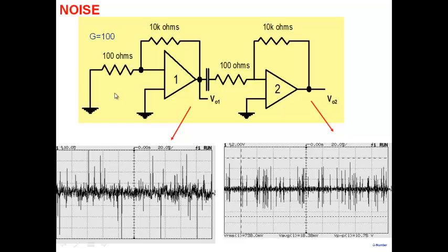It is coming from the fact that every resistor that you see here is a source of noise. This resistor is generating noise. This is generating noise. All of them are generating noise. By the way, the capacitor also has noise, because it has a resistance in parallel and other things. But more than that, if you go inside the op-amp, you have all these transistors. Inside a 741 op-amp, you may have 25 transistors sitting there, and you have resistors. Every transistor is a source of noise. Every diode is a source of noise. They're generating noise. Okay? So all these elements are generating noise.